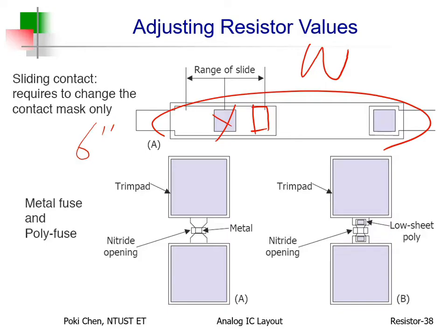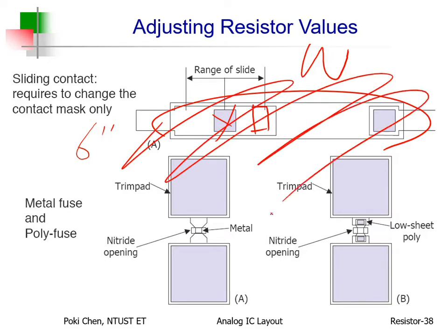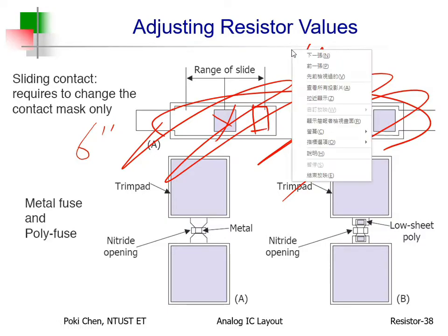And also, how to keep all those unfinished wafers not in the air, because oxygen will cause a lot of oxidation to kill the performance. So you need to put all those unfinished wafers into some kind of closet fully filled with nitrogen. Otherwise your semi-finished products are oxidized immediately and completely unusable.